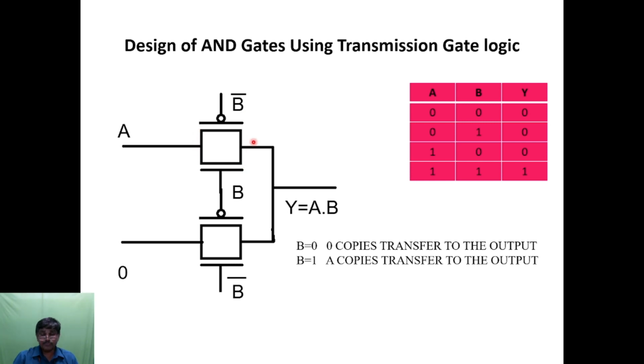So what is the difference between the previous case and the transmission gate? In the previous case, the output voltage or voltage strength is somewhat less compared with the transmission gate. A transmission gate is a bidirectional switch. When we give the control input, both transistors conduct simultaneously. When both are conducting, the voltage strength will be very high. So definitely the circuit has a proper voltage. It will not have less voltage strength. That is the concept behind this transmission gate.